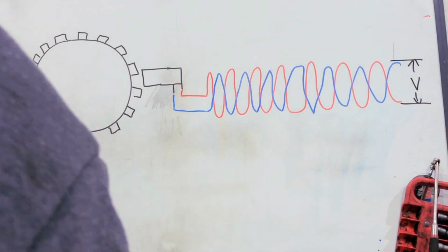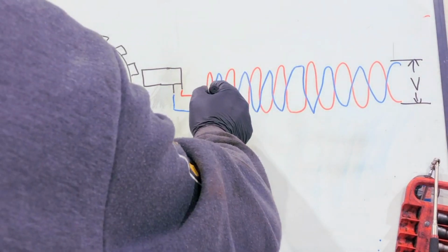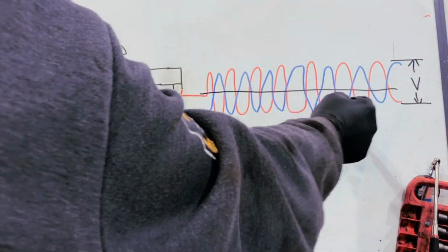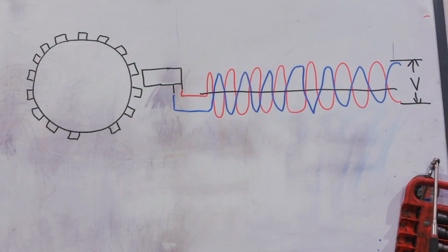So this is 0 through the middle. So we're looking for the same amount of voltage below 0 as we're looking for above 0. Now it does need to see a certain amplitude to be able to register the engine speed, and on an inductive sensor I would say anything above sort of 4 or 5 volts would trigger an engine speed signal.